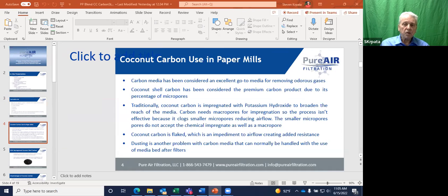And carbon media has a huge number of small micropores, so it's great for VOC control, volatile organic compounds control, which are in a normal gaseous state at room temperature. Unfortunately, there are more corrosive chemicals to combat in cleaning the air than VOCs.